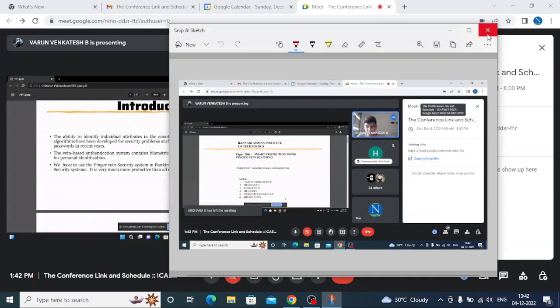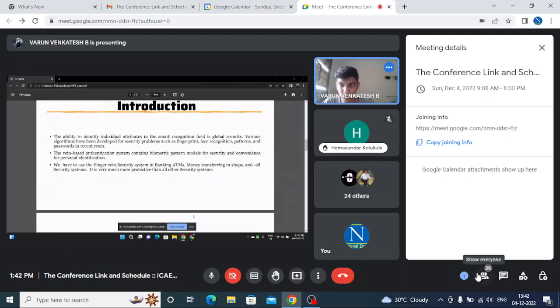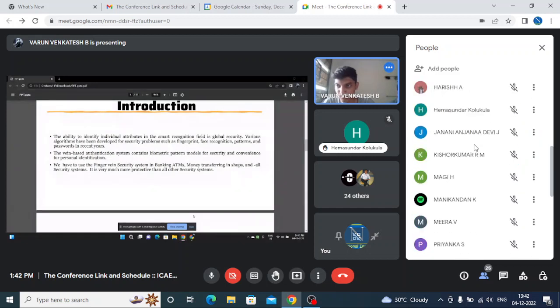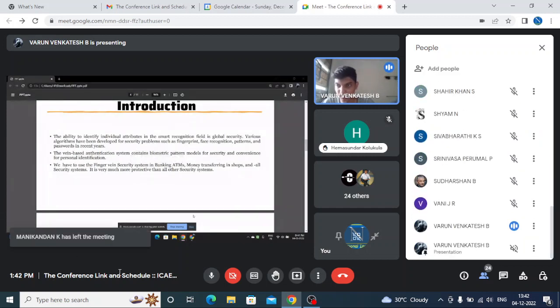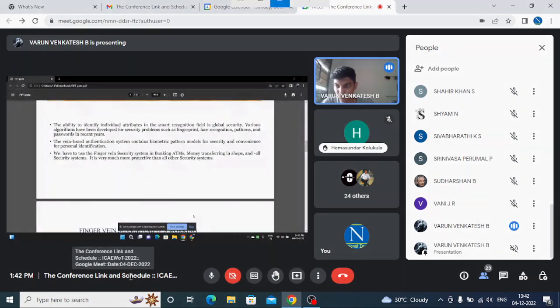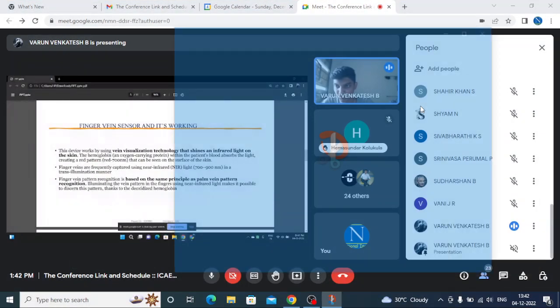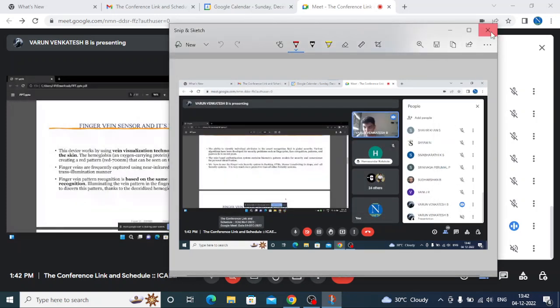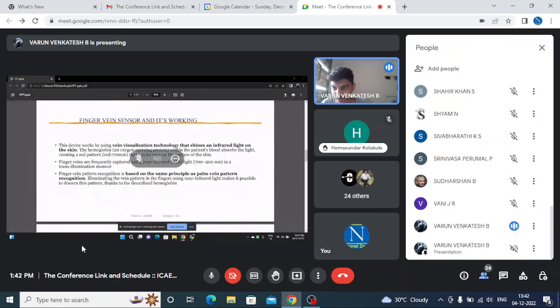This technique analyzes the pattern of blood vessels visible from the surface of the skin of fingers. It relies on capturing an image of the vein inside the hand by shining near infrared light on the finger. The hemoglobin in the blood vessel absorbs the light, which makes the vein appear as a pattern of lines. The camera records the image and the raw data is digitalized and sent to the database of similar images. The finger is scanned by a special camera in the same way as before, and the data is verified against the database of registered images. The whole process takes less than 2 seconds, sir.